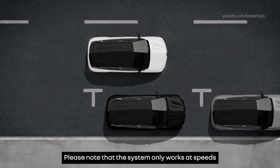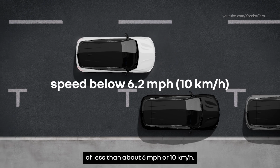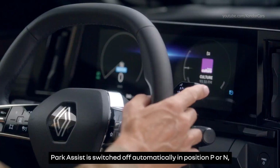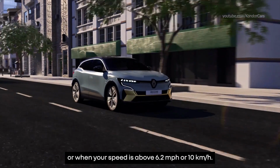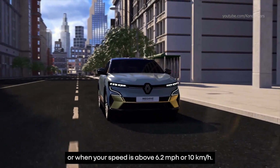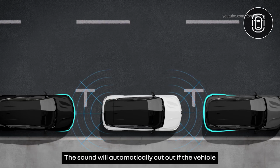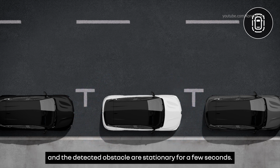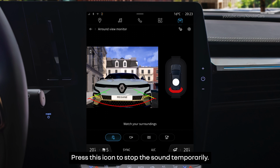Please note that the system only works at speeds of less than about 6 miles per hour or 10 kilometers per hour. Park Assist is switched off automatically in position P or N, or when your speed is above 6.2 miles per hour or 10 kilometers per hour. The sound will automatically cut out if the vehicle and the detected obstacle are stationary for a few seconds. Press this icon to stop the sound temporarily.